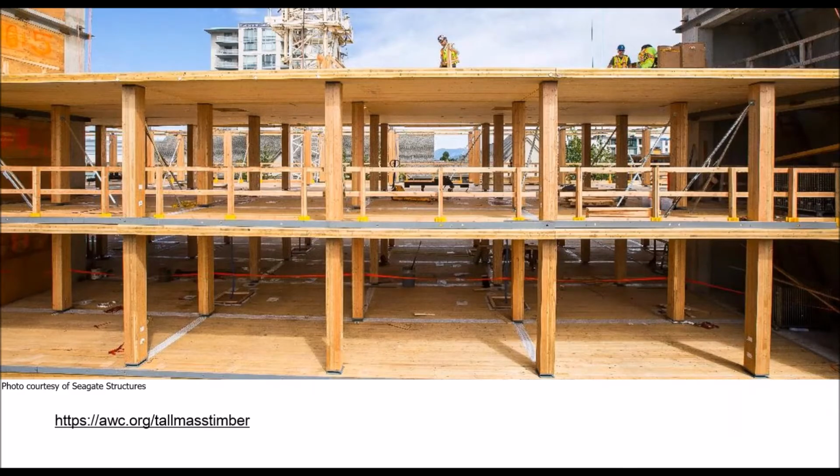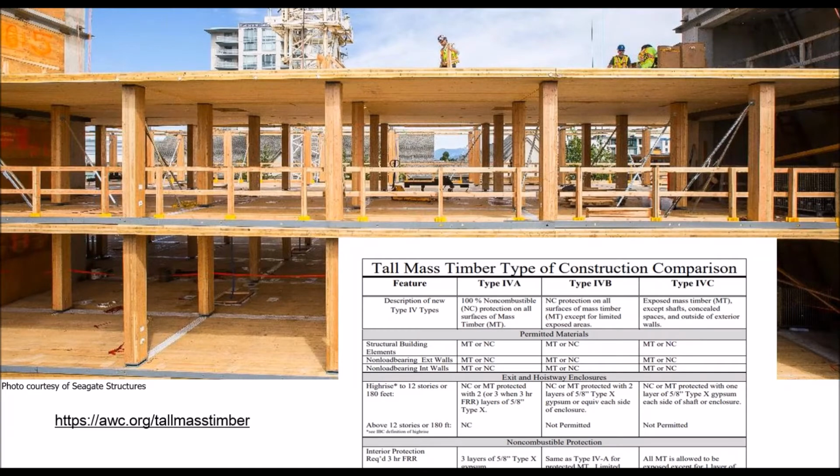Now, when we get into the 2021 IBC, I just wanted to give everyone a brief reminder of these new mass timber building types that are coming. We have Type 4A, Type 4B, and Type 4C. Our good friend, our old Type 4 construction, has been renamed. That's going to be Type 4 heavy timber. So nothing has changed about our historic Type 4 heavy timber building types. So these are the new mass timber construction building types.